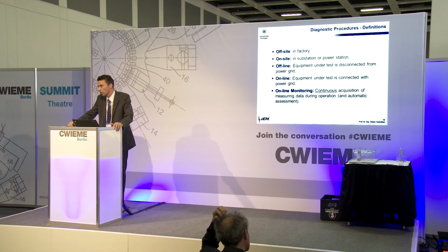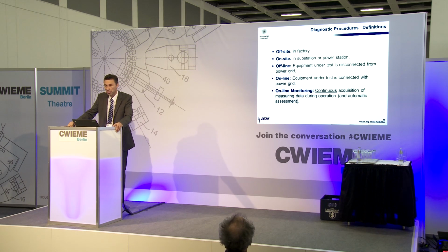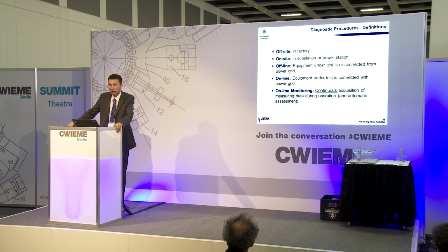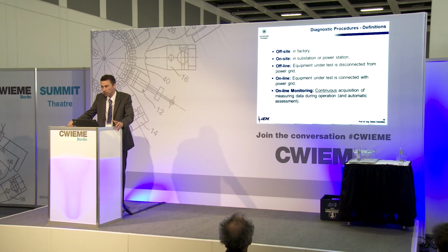So if you do an offline measurement, you have the advantage that you can control the voltage, but the disadvantage is that you need a generator to generate the test voltage, for example. So normally an offline measurement needs much more expenditure than the online measurement.